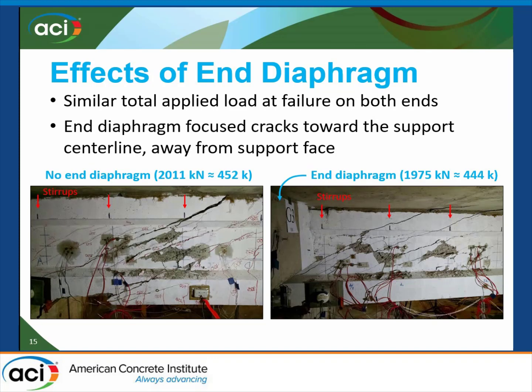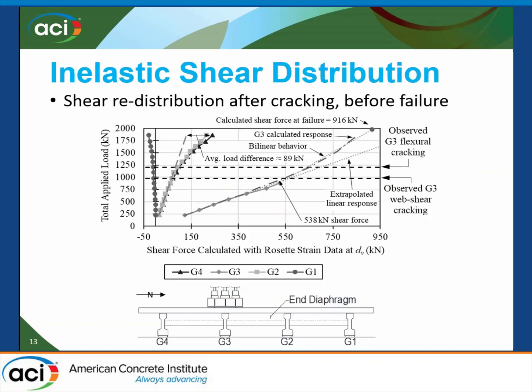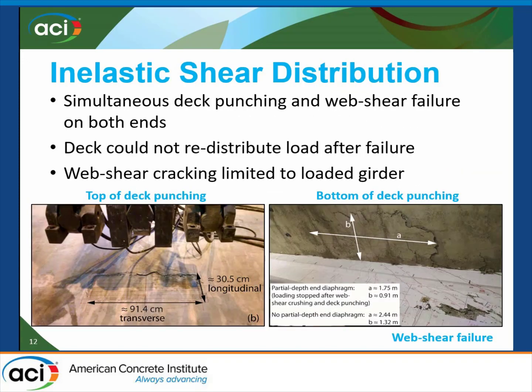I'm just curious, did you reinforce the deck so that the deck would properly distribute as in a real case? Yep. I didn't mention much detail about the deck design, but it was 9 inches thick and had the normal reinforcement the state of Minnesota puts in a 9-inch thick deck, transversely and longitudinally. So it itself should have been able to handle, to a certain point, what we did.